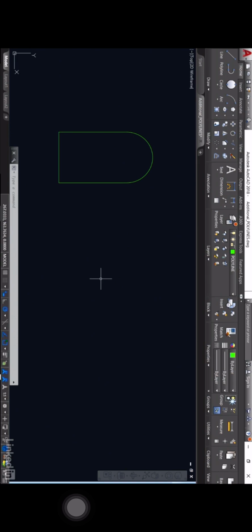So let's have a look at that. Let's see how I can do that. So what I'm going to do is I'm in essence going to start here. Can you see that crosshair where it is now? There's a line ending there that goes into that arc segment of the polyline. So I'm on the polyline layer here, like so. So make sure you use the polyline layer.